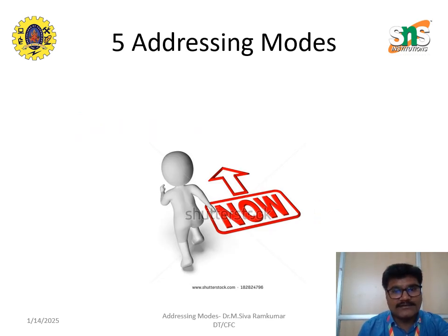First, we have immediate addressing mode. Here the operand is directly specified in the instruction itself. Think of it as packing your lunch. Everything you need is already in the box. For example, MOVLW 0x55 means moving the literal value of 0x55 into the working register WREG. Why is this useful? It's super fast because the data is directly available. Use it when you want to load a constant value to a register. Can you think of a situation where this might be useful in your projects?